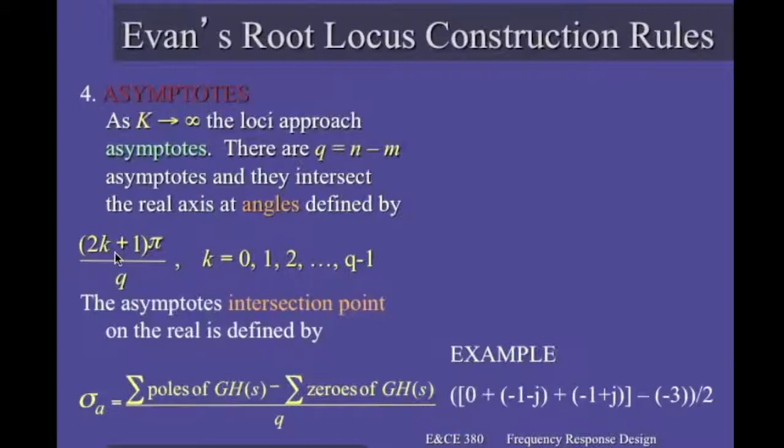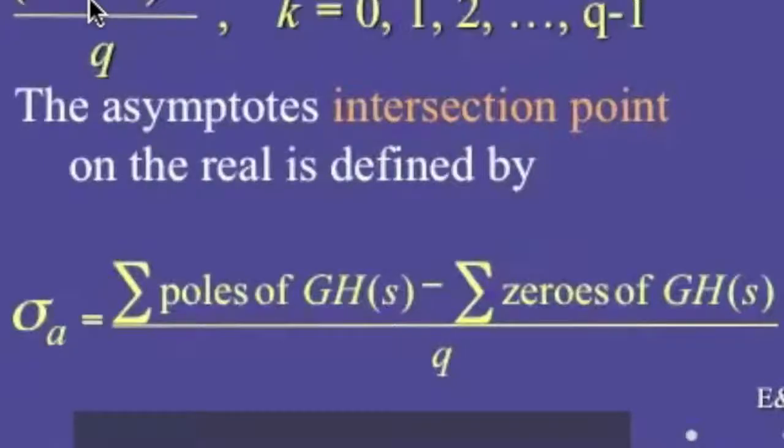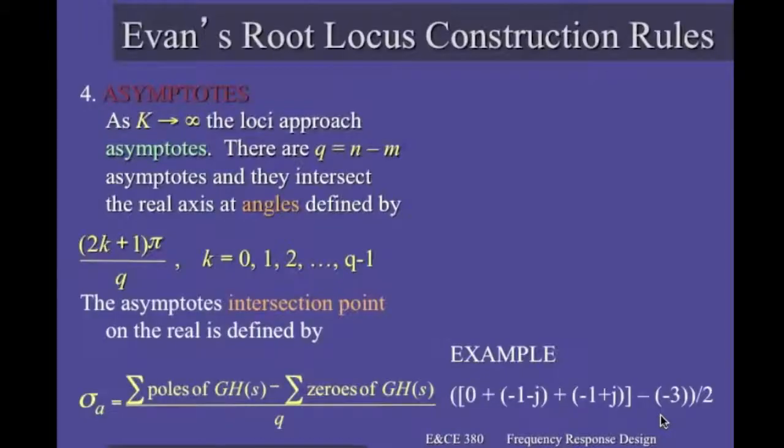The next point is, where are those asymptotes located? Or better, where is the intersection center? They define a family of straight lines all centered in one point, which is the gravity center of the asymptotes, and can be calculated by this formula. They move to infinity, one to plus infinity, and the other one to minus infinity, by approaching the asymptotes, as k is increased from 0 up to plus infinity.